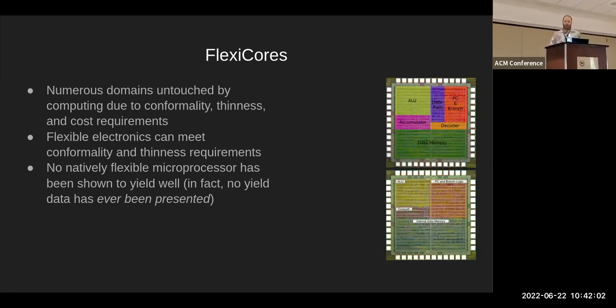And due to scribe and crack stop ring sizes, if you actually tried to make them that small, you'd end up wasting the vast majority of your wafer. So the issue with doing something like this in silicon is you wouldn't actually be able to achieve those ultra low prices just by making a really small microprocessor in silicon. The second part of your question, do you mind repeating it?